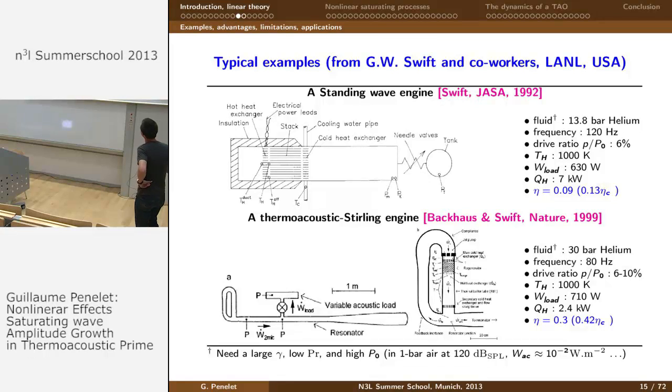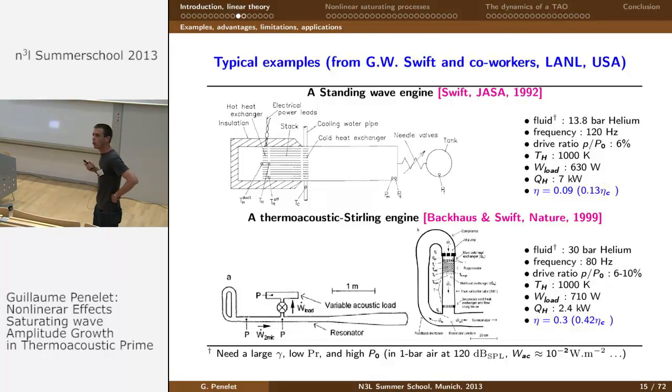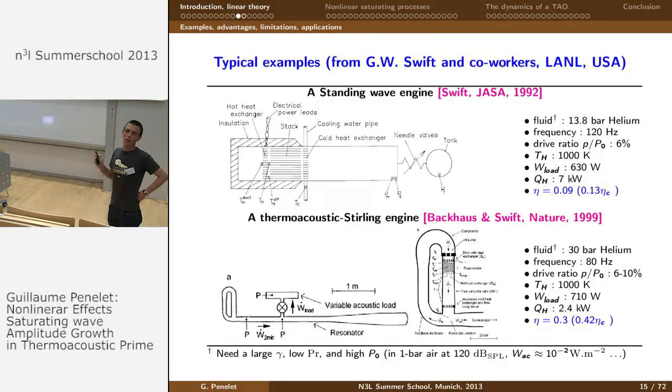So here are two examples of thermoacoustic engines which have both been designed at Los Alamos by the team of Greg Swift. So this is a standing wave engine, so we recognize this straight duct. We have a standing wave, this is the stack, and this is the acoustic load. And this device can provide up to 600 watts of acoustic power to the load with an overall efficiency which is almost 10%.